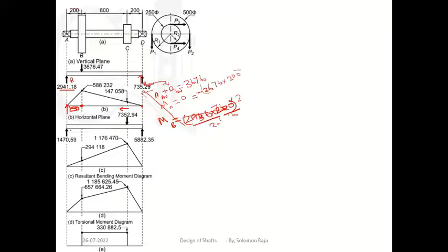Now we have to draw the same line for horizontal forces. In horizontal, P4, P3 is acting on C. Okay. So let me take the horizontal forces. I have drawn both horizontal forces like this. I can't draw like this. At C it is acting like this, so I can't draw the forces like this. I have to draw the horizontal line only. I have to convert the horizontal force into vertical direction. That's all. Okay. Add P3, P4. If you add P3, P4 you will get